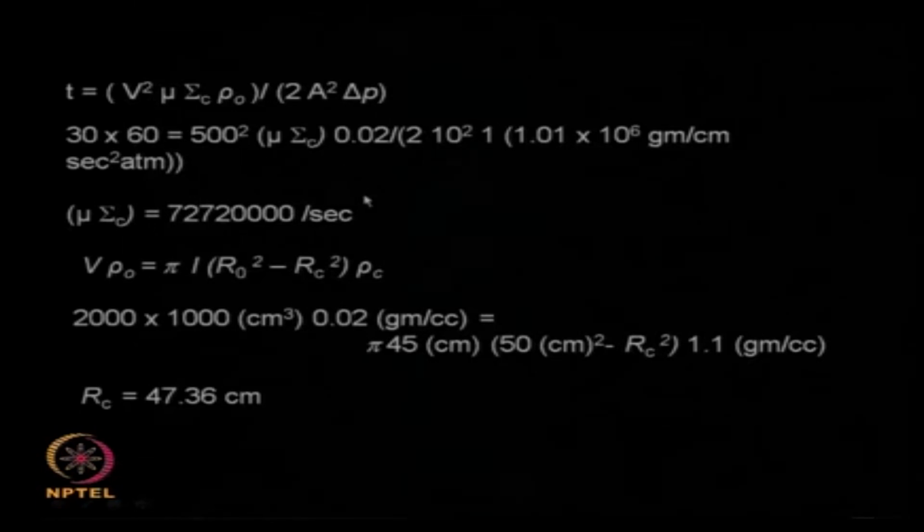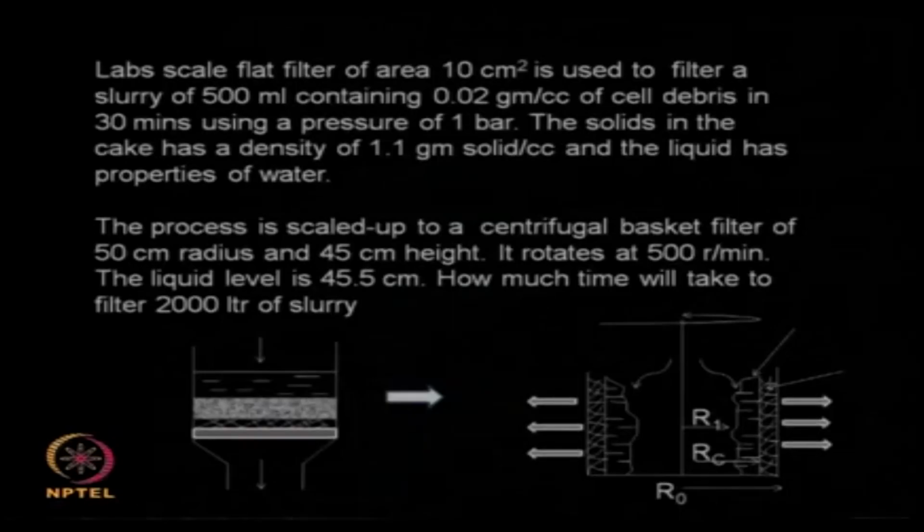Okay. Now we need to calculate the thickness of the cake in the centrifugal filter. So how? You can do a mass balance from this particular data set.